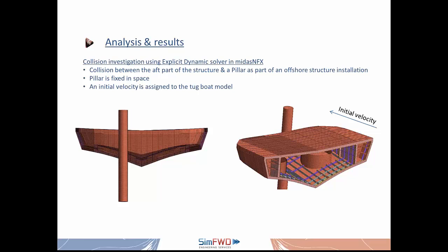So ideally, this pillar is fixed in space, and we assign through the Midas NFX tabs for the nonlinear analysis the ability to assign an initial velocity to the tugboat model. And of course, we have to very carefully define a contact between the two parts, between the pillar and the tugboat.